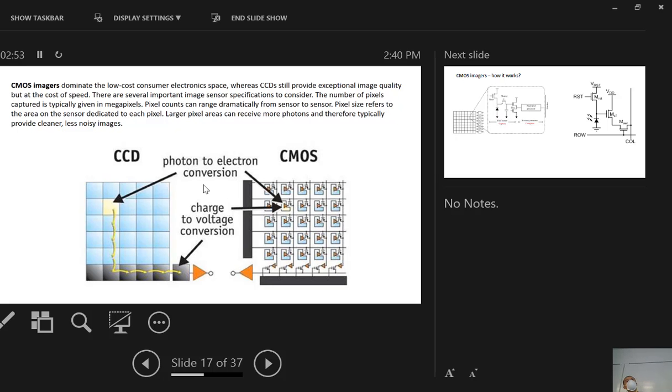If you open up the lens of a high-end camera, you can twist it and look inside, and you can see a chip inside. Have you ever seen that before? The surface of that chip reflects the light, becomes purple and colorful. That's the CMOS chip. The cover is usually a filter, and right underneath the filter is the passivation layer of the CMOS chip, just silicon dioxide. And underneath that will be the top metal of the CMOS chip, just all the metal traces.